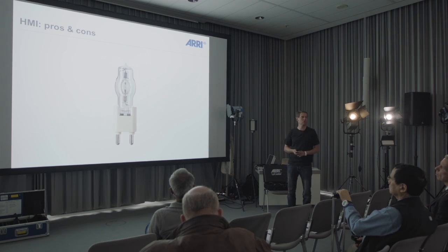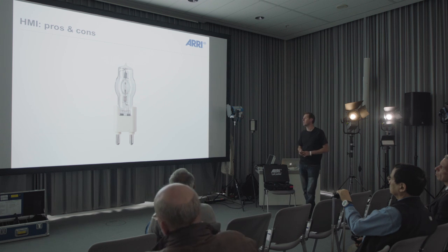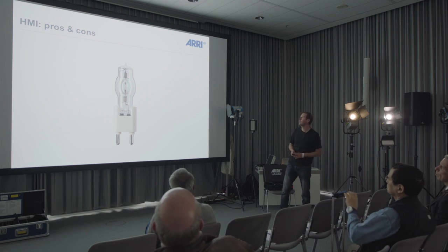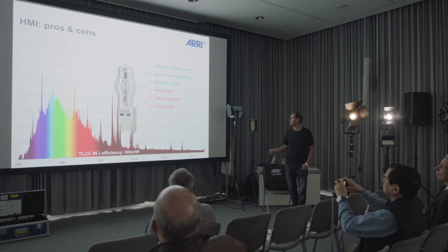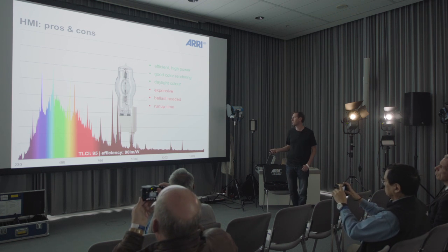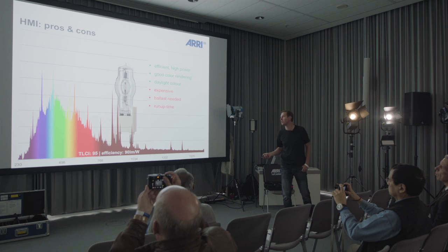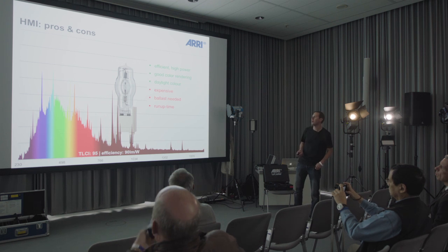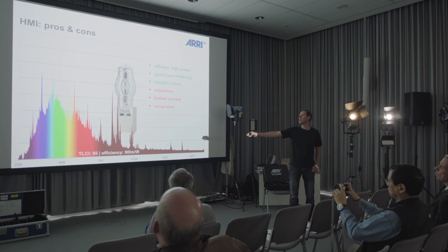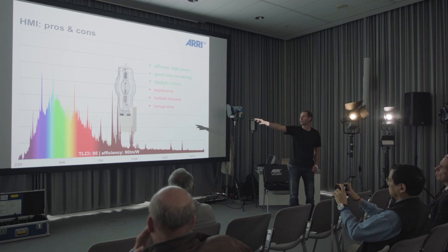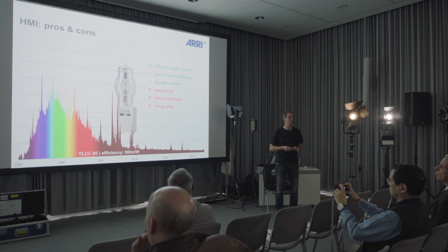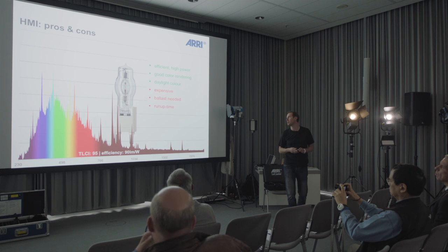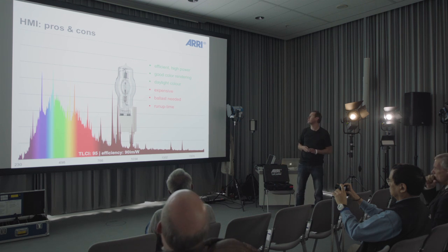Second technology that we use a lot, especially in movie lighting, HMI, this is much, much more efficient. Just here, 90 lumen per watt. Sometimes it's even 95. So a very, very efficient technology, HMI. We have HMI fixtures over here. These three are HMI, and absolutely important technology for all movie productions. So there's no way to get around HMI.